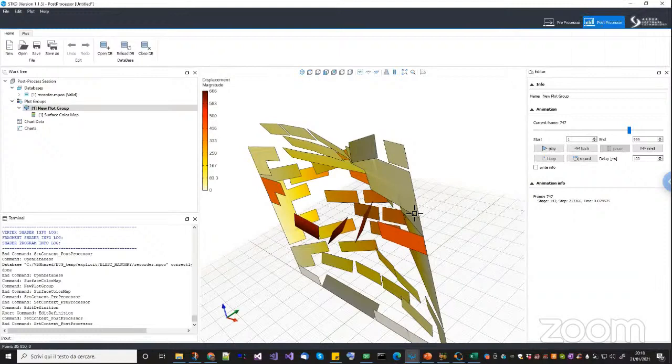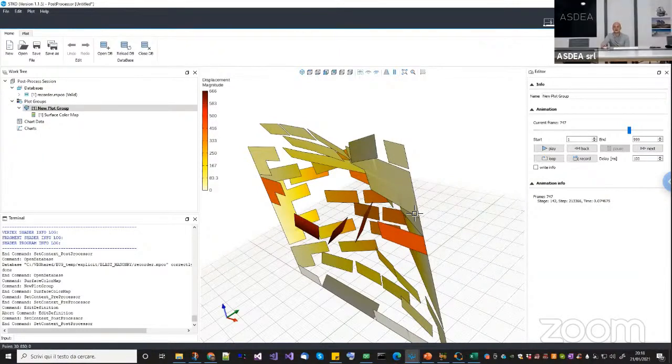Can we do an IDA using Tcl scripting? Yes, using Tcl, provided that you know enough Tcl, you can do whatever you want. This is the nice thing about OpenSees, that since it is programmable, you can do whatever you want. Some things are easy, some are more complicated, but you can definitely do it.